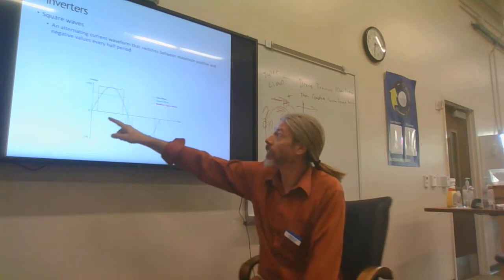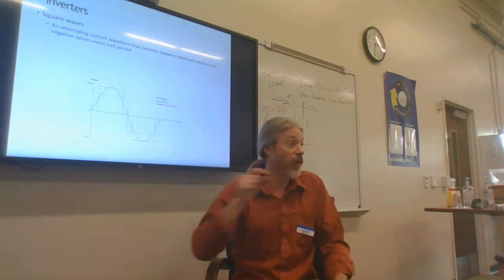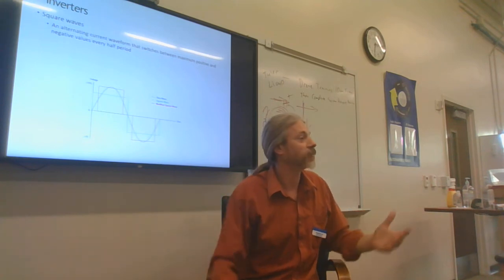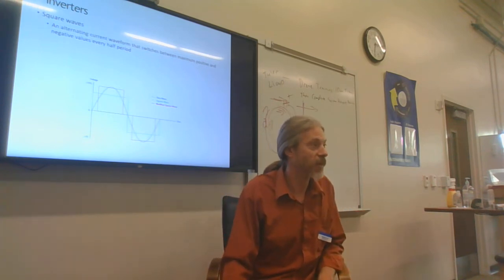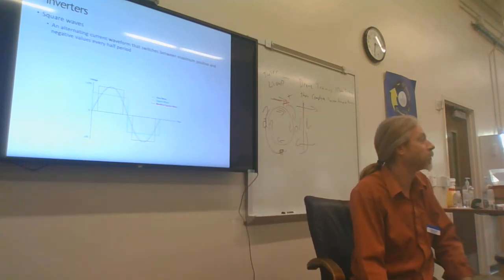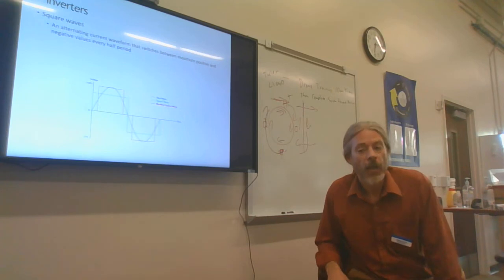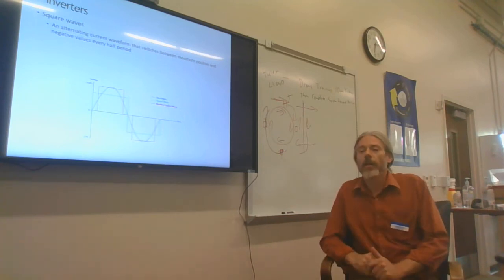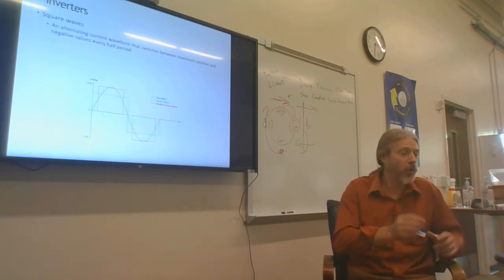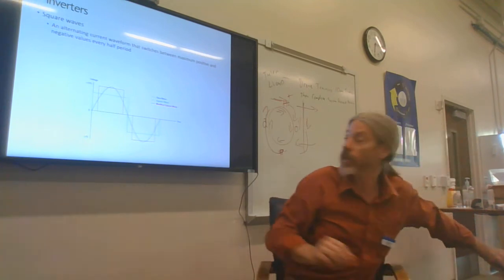Due to the duration of that time, it's putting the power in too long. There you go. That's exactly right. And so that additional heat buildup will make the motors go bad. And the other issue sometimes is they just don't have the true torque or the energy that we need.